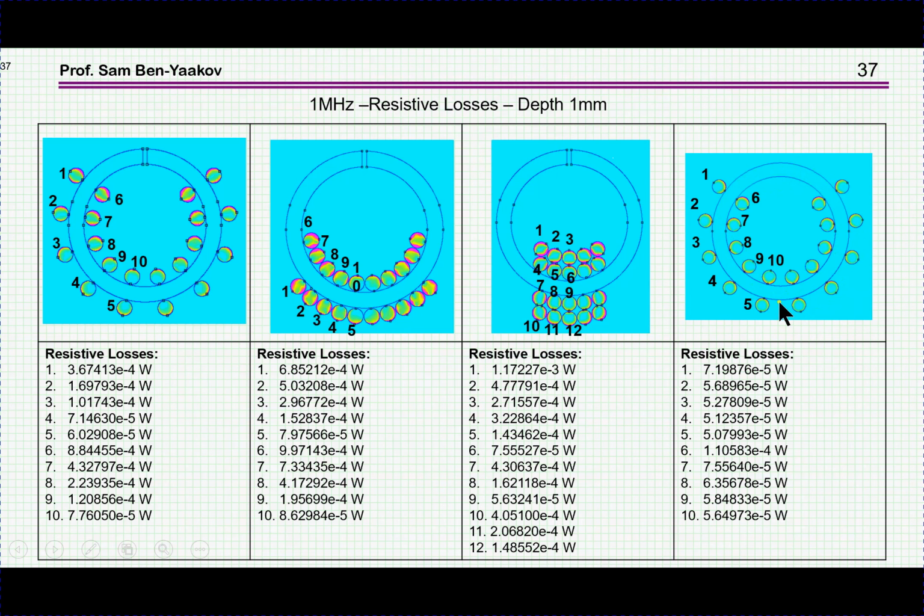But core losses will be very high if you use it for resonant converters. However, for the case of regular PWM converters, in which the delta I, that is the ripple current, and therefore the delta B expected in the core is small, the iron powder core will have an advantage because the losses due to the skin effect and in fact the proximity effect will be much lower, considering the fact that the magnitude of the AC component of the current is much smaller.